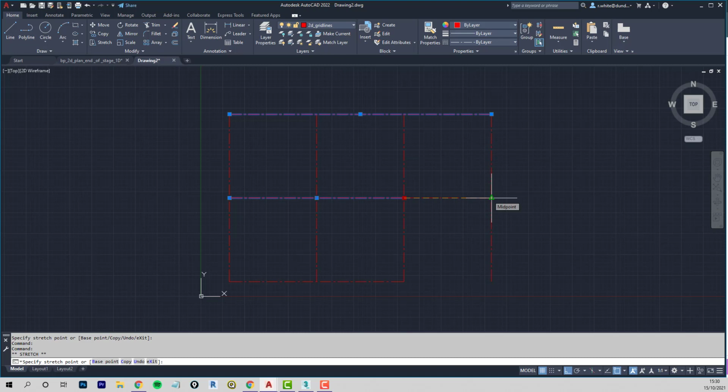Now watch what happens if I tap my tab key here. It will go through the various object snaps that could work for that line. So if I tap the tab key, perpendicular is okay, endpoint no, endpoint no, midpoint is okay as well. Do you see how it's cycling through them? Midpoint, perpendicular, sorry, let me do it again, I accidentally pressed click there. Midpoint, perpendicular, endpoint, endpoint. It's cycling through them until you get to the one you want.